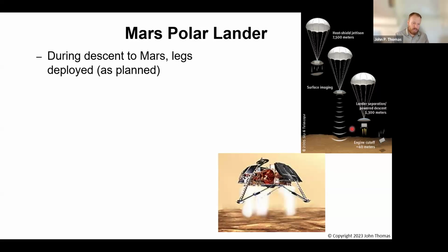And when the computer comes down to the surface and touches down onto the surface, there are sensors in each foot pad. So there are 3 of these feet, 3 of these touchdown sensors. And the computer will look and make sure there's agreement in these 3 touchdown sensors that we have indeed touched the surface. These are basically vibration sensors, if we simplify it a little bit.